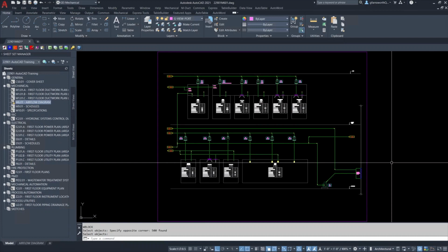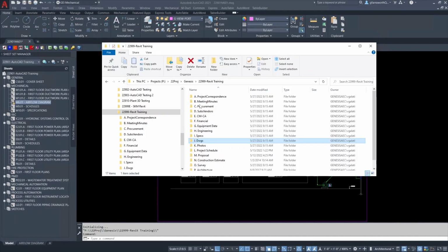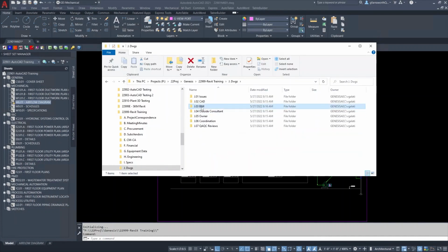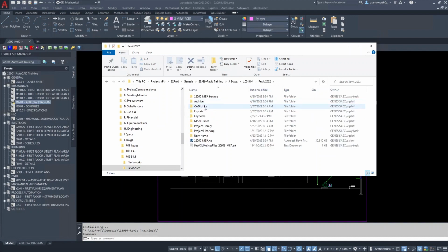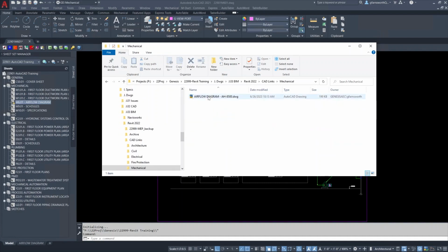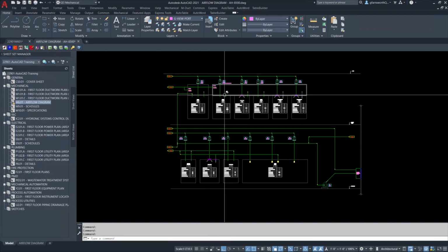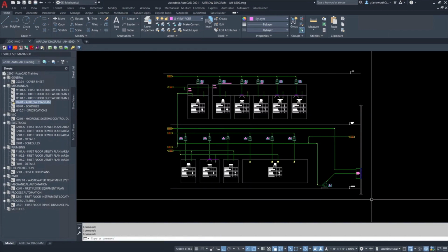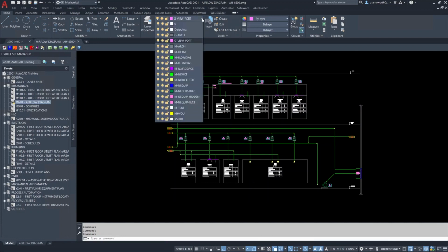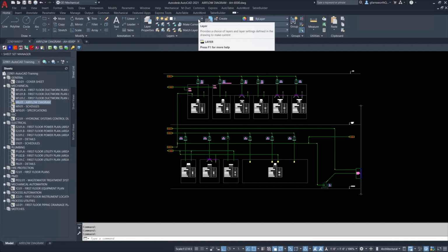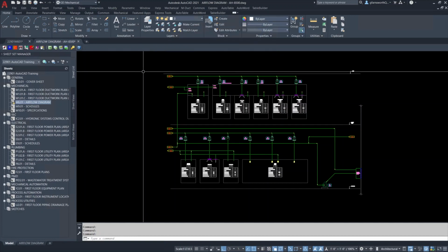Now that we've exported the drawing elements we want, we need to clean it up. Open the drawing you just made. For an AutoCAD drawing to display properly in Revit, Layer 0 must be on, unlocked, and thawed. Since I'm not doing any more drafting work in this drawing, I like to set Layer 0 to the current layer to ensure that it is set correctly. Also, since 0 can't be purged but other layers can, setting to 0 ensures that all purgeable layers get purged.